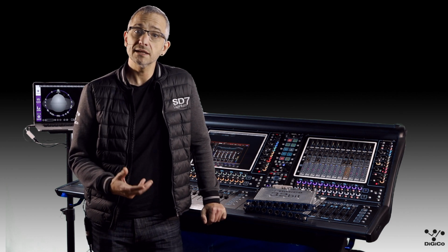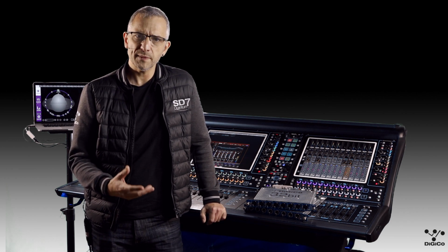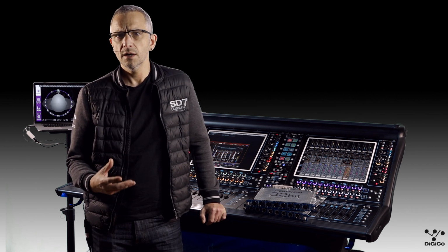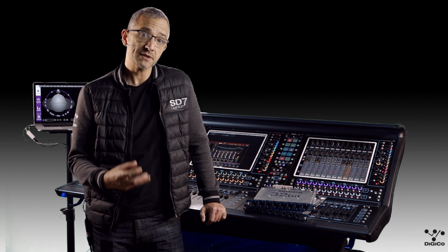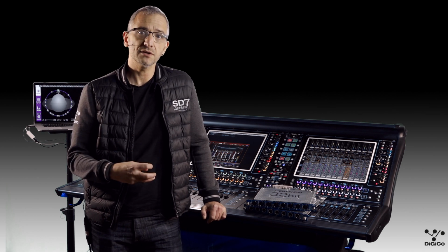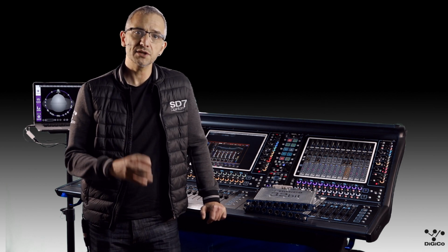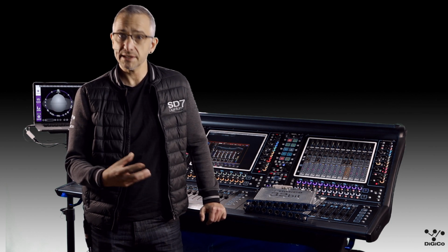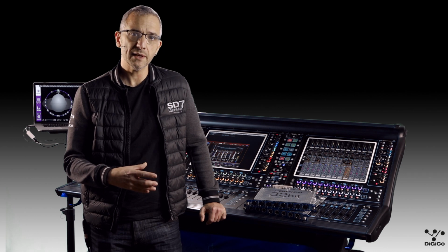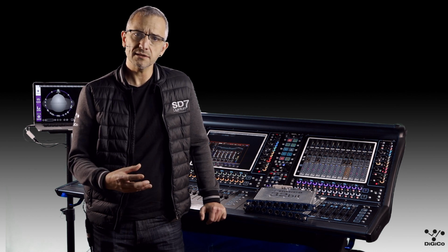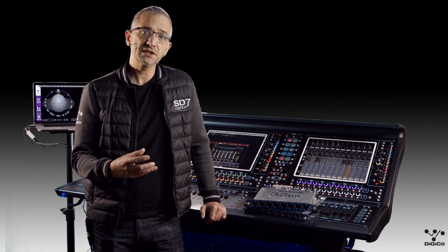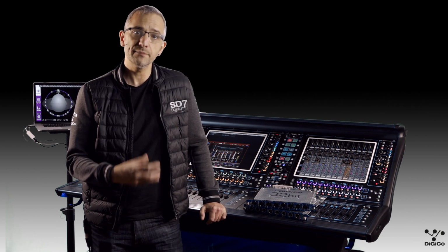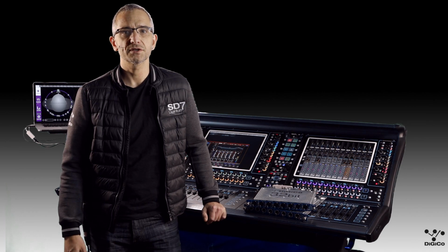Again, the answer to this is pretty simple. We've talked about the noise and how we've designed a card with an incredibly low noise floor, but any noise present as part of the preamp stage and 32-bit conversion is in the lower bits of the digital signal. So in order to use our 32-bit signal in a 24-bit system, we discard the bottom 8 bits. And this is, of course, where the noise is. We have our pristine 24-bit signal with a significantly lower noise floor than previously possible with 24-bit converters.